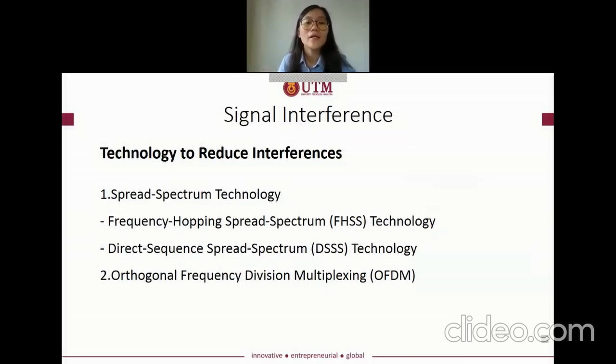On the other hand, the DSSS transmitter allows the spreading of the signal over a full transmission frequency spectrum. The main characteristic of this technology is redundant bits sent with each bit of data in order to increase both safety and reliability. In this case, the impact of interference and background noise can be reduced. Although this technology provides greater security and signal delivery, it is a sensitive technology that may be affected by many environmental factors.